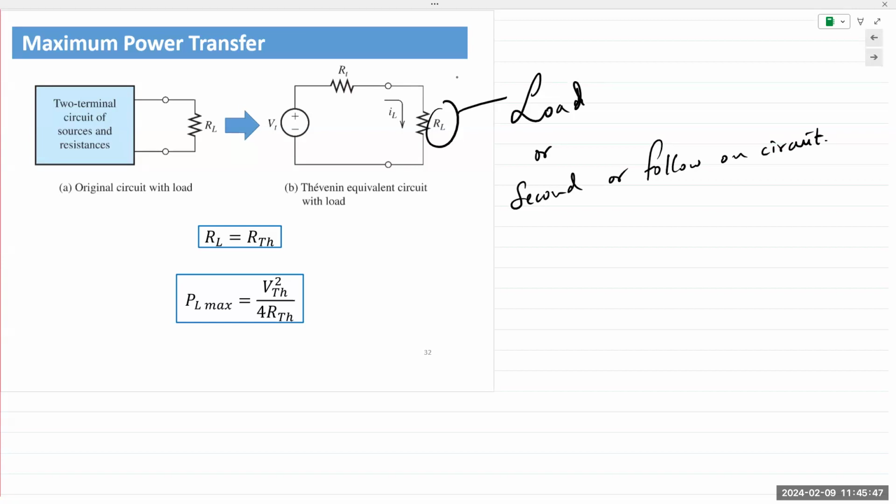If you go online, you can check out the PDF manual for any audio video receiver or an amplifier. It will always have a spec that says 100 watts, 2 channels into 8 ohms. It means you should connect an 8 ohm speaker to that particular amplifier. If you connect a 4 ohm speaker to an 8 ohm amplifier, it's going to supply a whole lot more current than it needs. Your speaker coils will burn out.